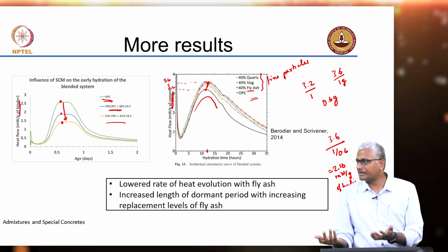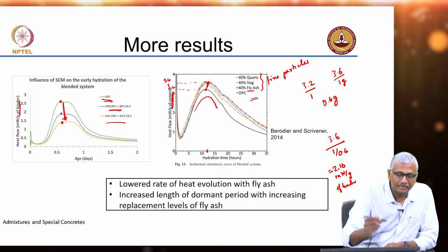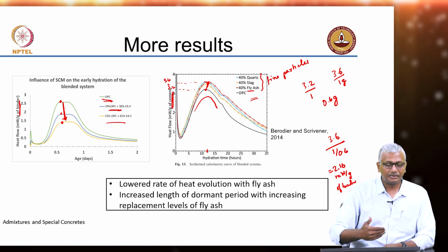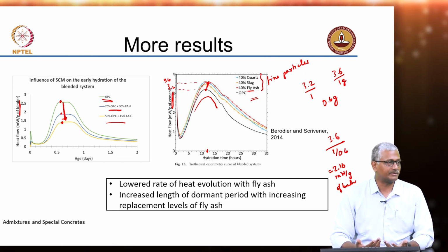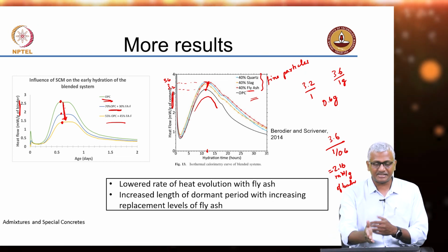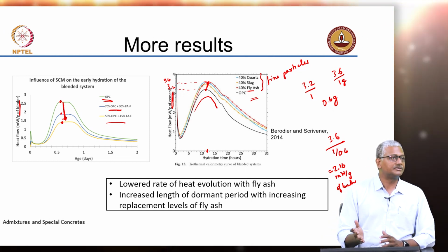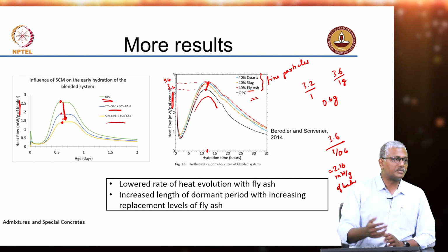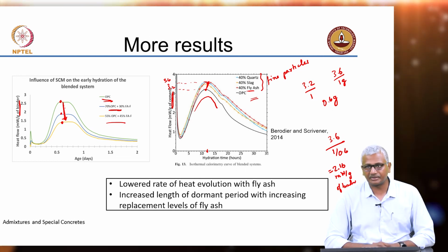It is not imaginable, right? Because you clearly see that when you add fly ash to 45%, your overall heat flow is actually reducing. You expect that. But when you present the same in terms of gram of cement, you are clearly going to see the effect of the presentation in the form of cement hydration getting accelerated. Okay.